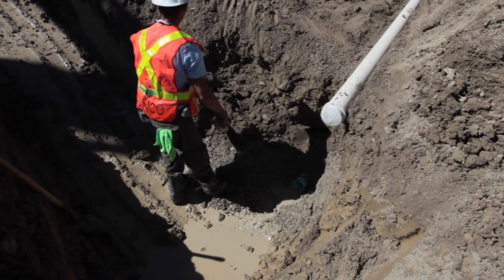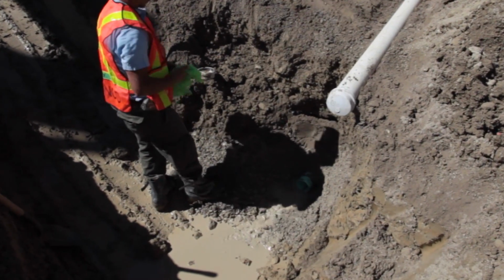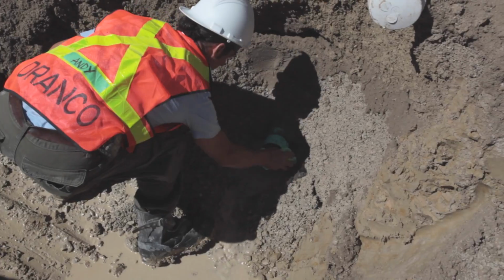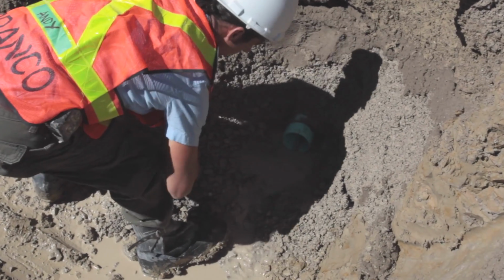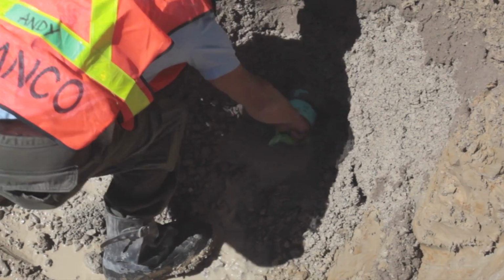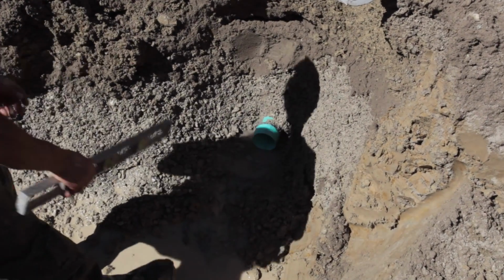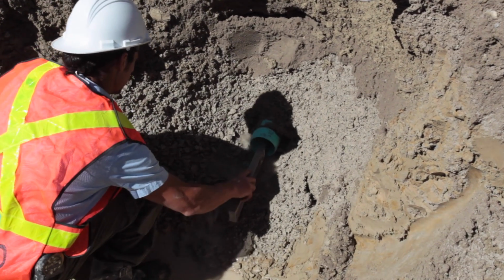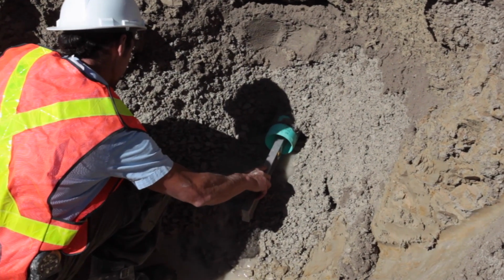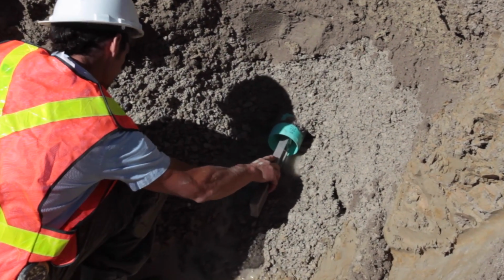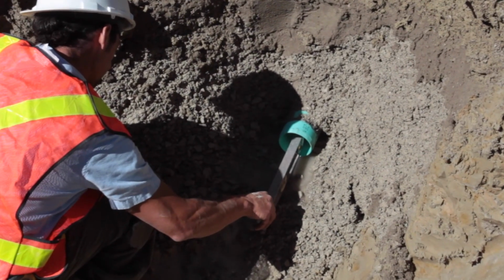We have located the green sanitary sewer pipe. We inspect the inside of the pipe, and using a clean cloth, we wipe off any debris or moisture. With a level, we check to confirm that the service sewer pipe has the proper minimum 1% slope. This equates to 1/8 of an inch for every foot.